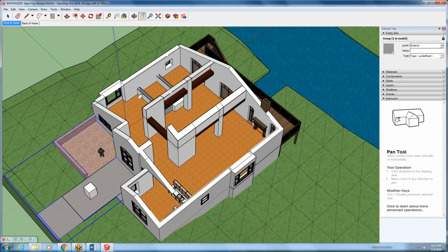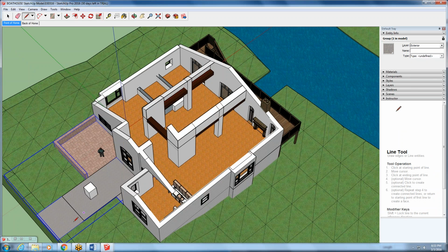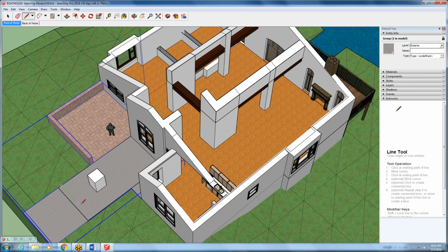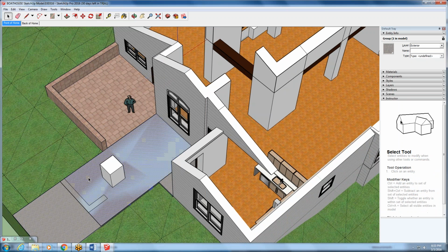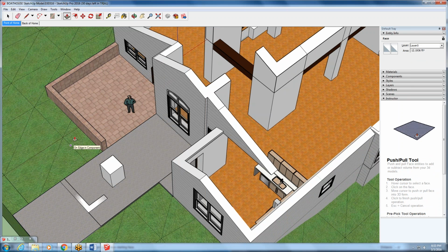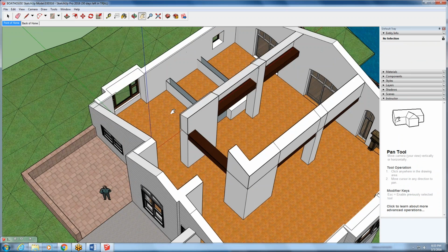And you don't have to do them as completely separate. You could come through and draw them as if you wanted to, those dimensions, and it only works this way because this is already like this, but just do it as a whole thing, one whole object. It doesn't have to be 2 pieces of wall. You could draw that whole shape in there as your outside walls of your room. So it really should not take that much time. I know you're learning it and you're playing with it, but it also shouldn't be that scary because it's just the one corner you're playing with. And I've locked the floor and walls so you can't stick to them. Okay, so that's the majority.